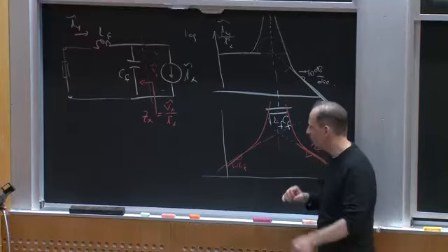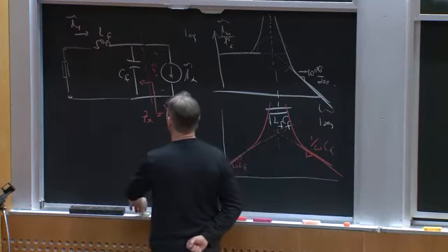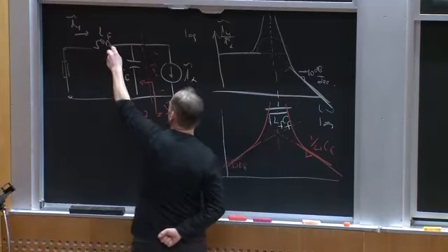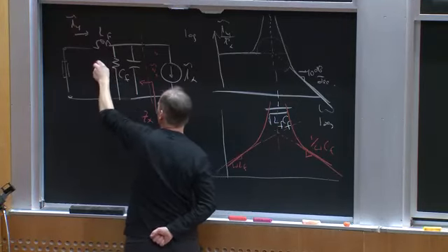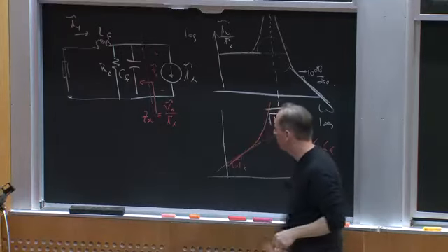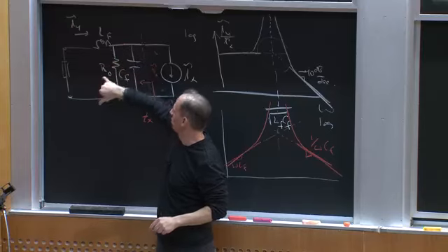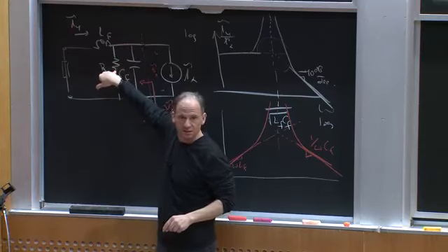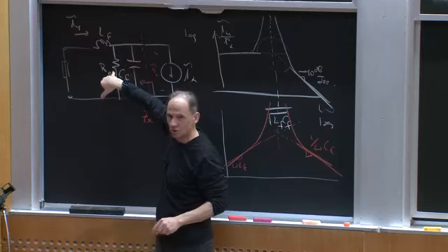Now, the most natural thing to think about doing in a filter is maybe just putting a resistor. Maybe I could put a resistor, I'll call it a damping resistor, RD, right here. What would RD do? Well, if LF and CF are at resonance, RD is the only thing left, because these kind of cancel each other, and my output impedance would just go to RD.